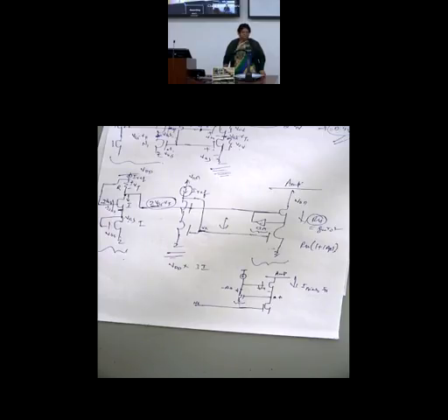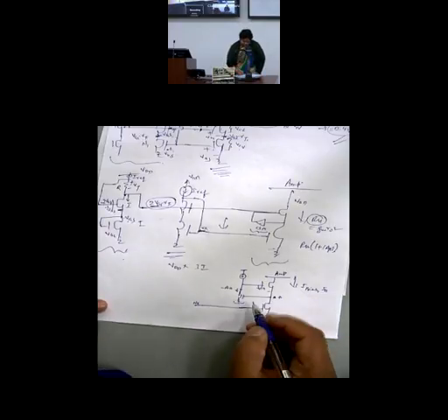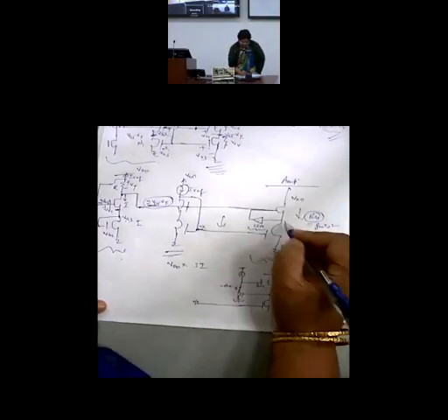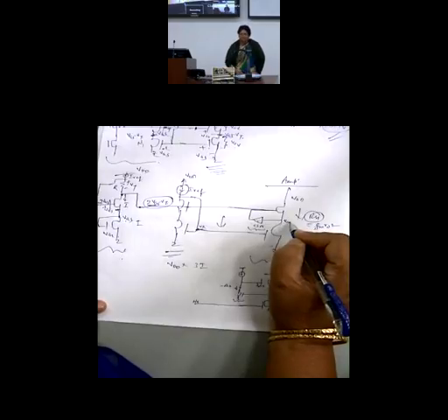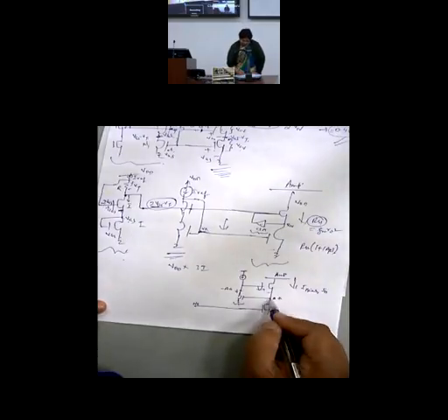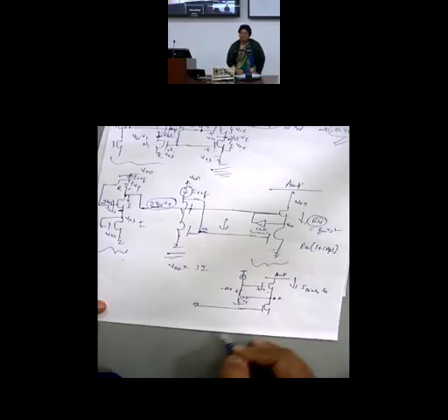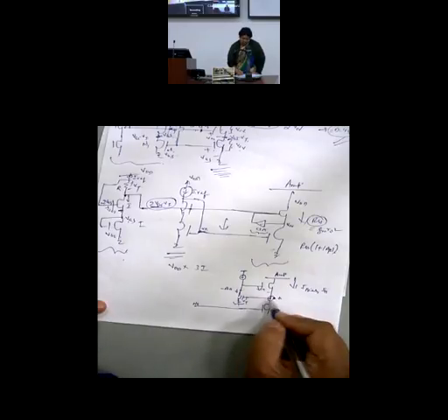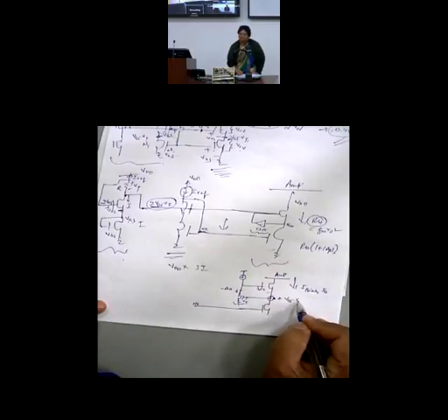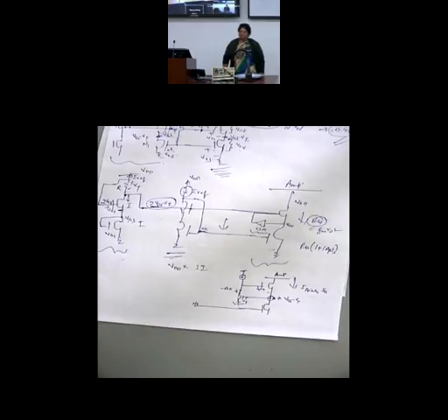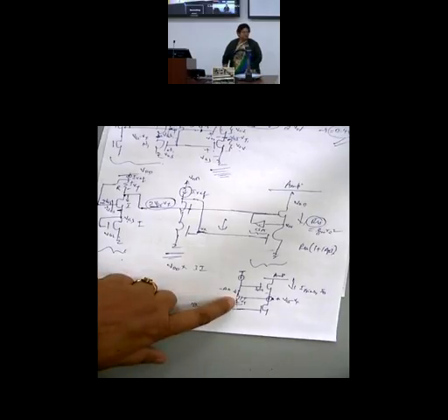Clear? But there is a problem now. Remember, we have brought it to 1 VT overdrive. But now, because this is a diode connection, I cannot have it less than 1 VT. So this cannot be brought to VGS minus VT. You cannot make it operate at 2.2 volts. Otherwise, this MOS common source amplifier will not operate. So I have a drawback. So I modify my feedback.